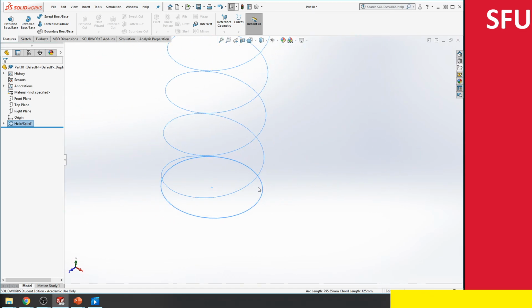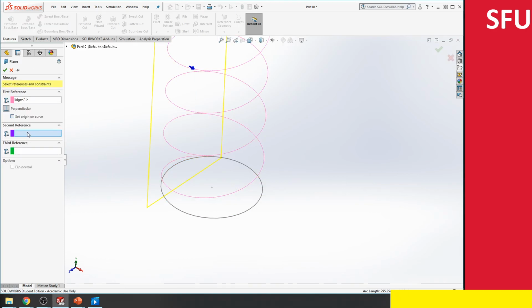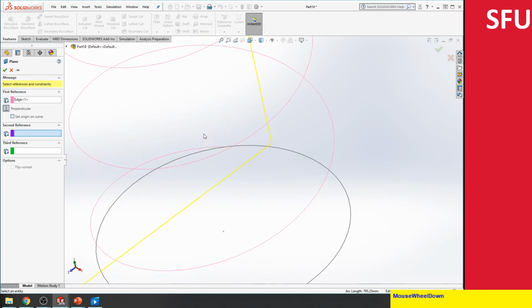Now if I wanted to create a spring, so what I do is I select this curve, and then I'm going to create a reference geometry, create a plane. So the second reference, I'm going to use this end point. So make this perpendicular.